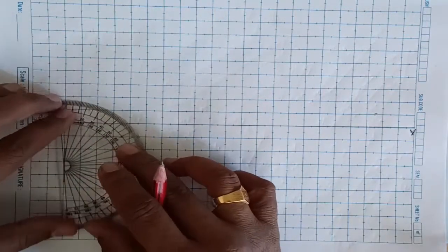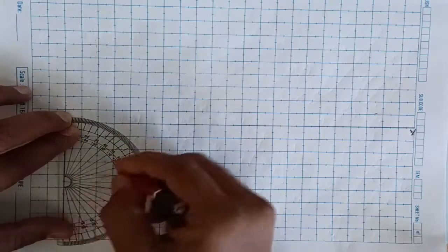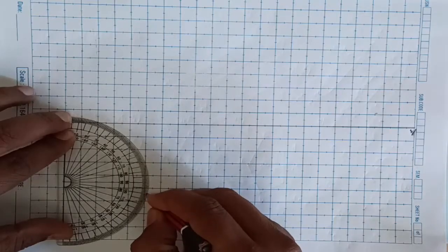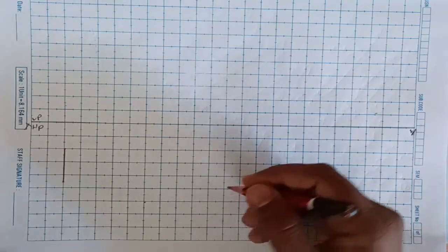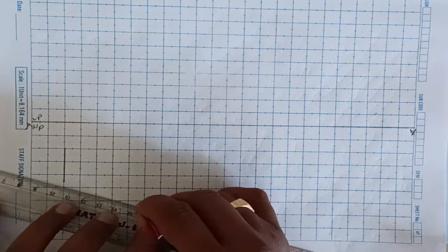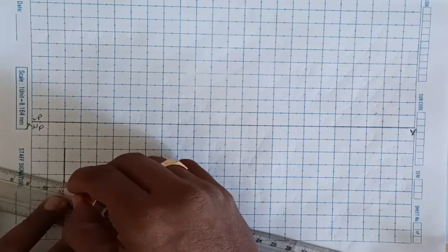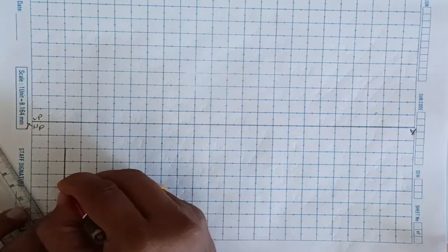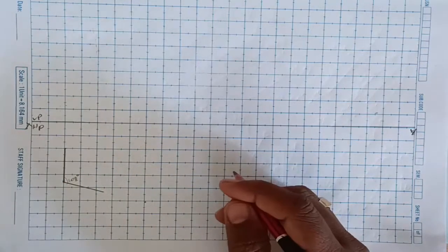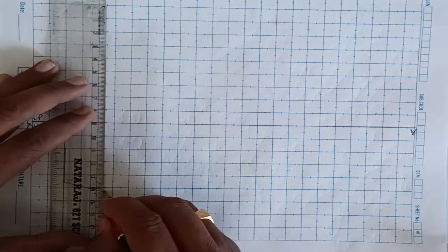And next, we know that the inside angle of the pentagon is 108 degree, so from any one corner we need to measure 108 degree. Mark it, and passing through that point, we need to draw a line of length 25. We marked it, and you can show the angle if you need it. And for the remaining, there is no need to measure any angles; we can do it directly by drawing projection lines.